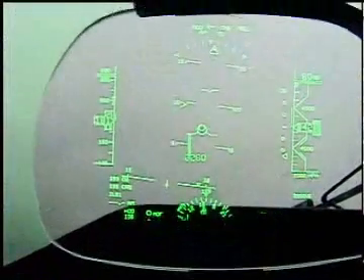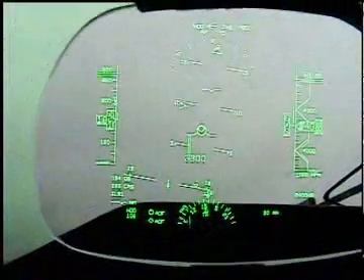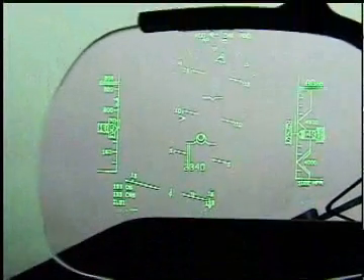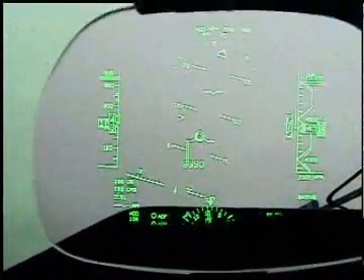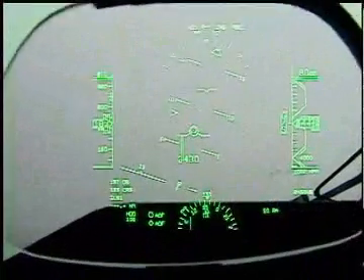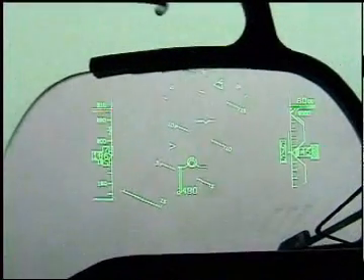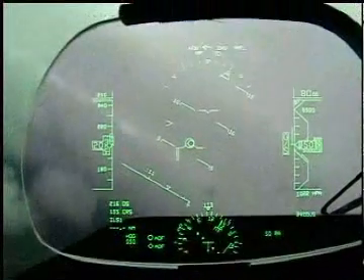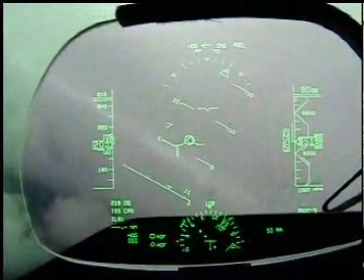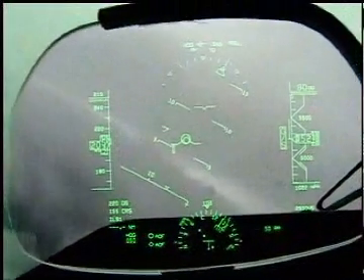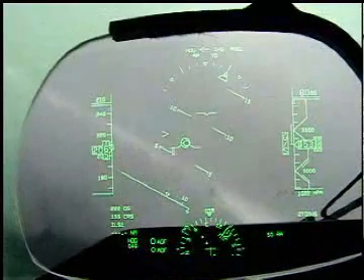When the flight director mode changes from takeoff to a different mode, the flight director guidance cue and speed error tape are displayed. Radio altitude and the HSI appear after rotation. However, the HSI symbology may be only partially displayed due to display compression at high angles of attack.